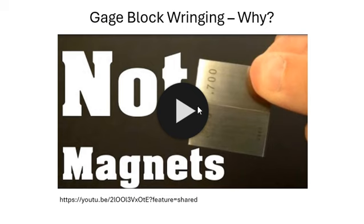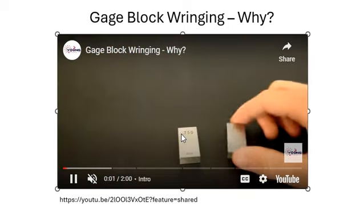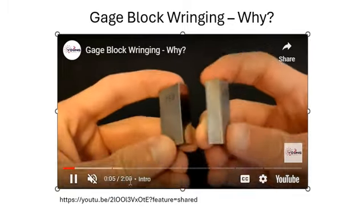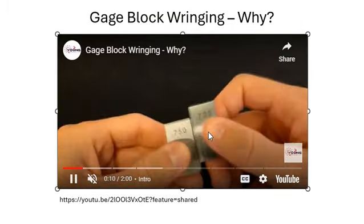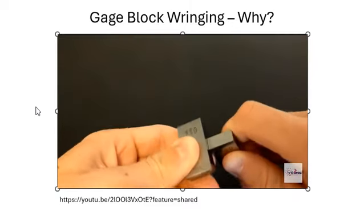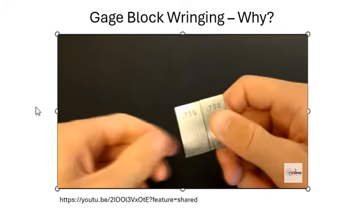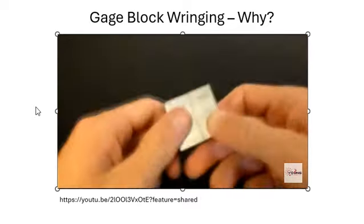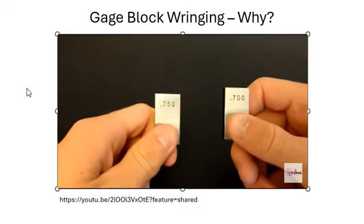This is another YouTube link on gauge block ringing, and again you can watch it. This is a little bit shorter video. Of course you can see this gauge is hardened steel. The very first video that we showed had a ceramic gauge block. See how he applied the pressure, and then turned 90 degrees. This is a pretty clean gauge block, so they stack together pretty well.